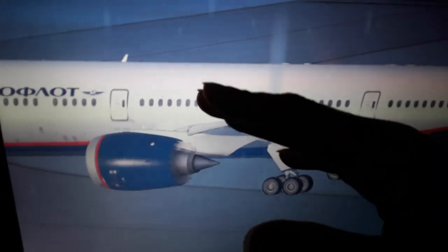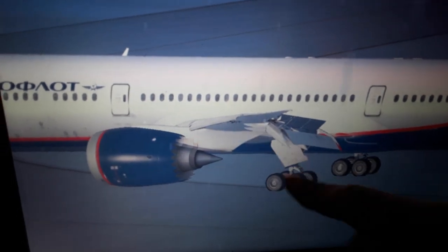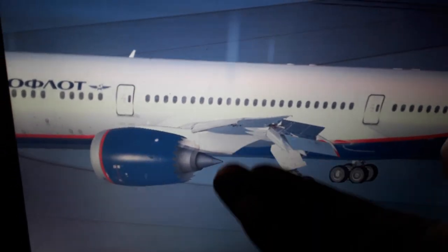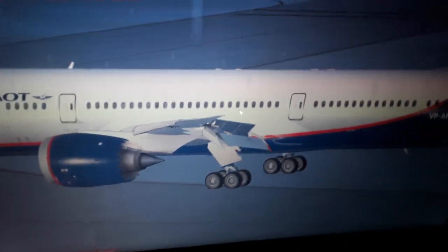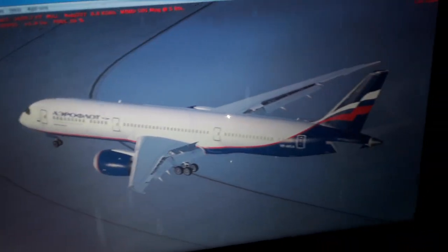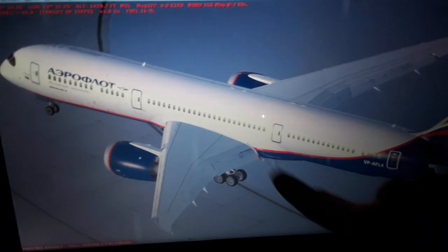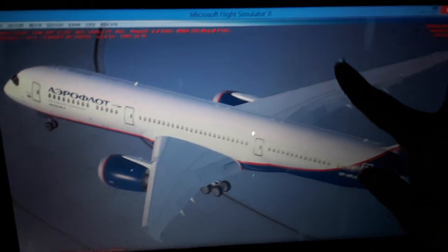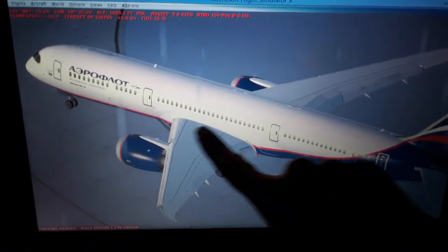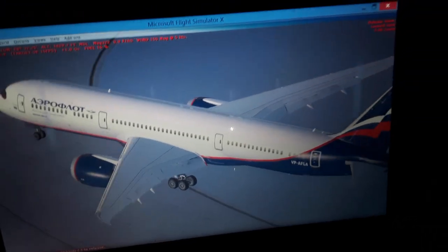As we fly we have also an angle of attack that usually is positive, so the airflow is moving slower below the wings, which creates a higher pressure below the wings, which pushes the aircraft wings and weight up into the air. Also the top surface of the wings, you can see the airflow is moving faster, using the Bernoulli theory of fluids, so we have lower pressure, which sucks the aircraft wings and weight up into the air as we fly.